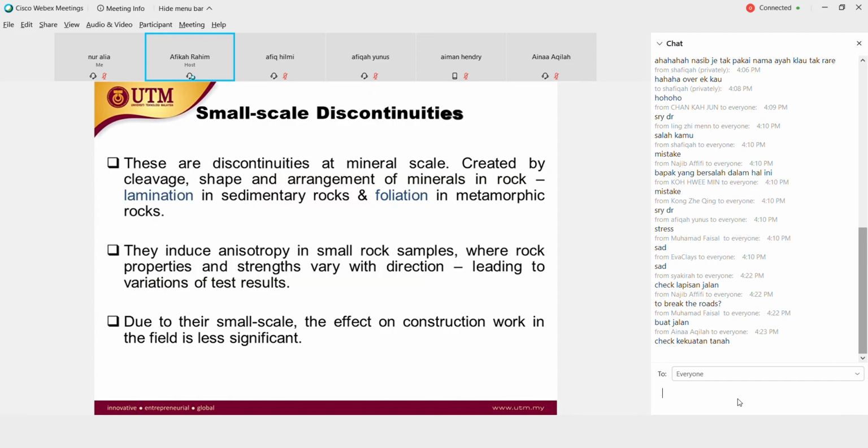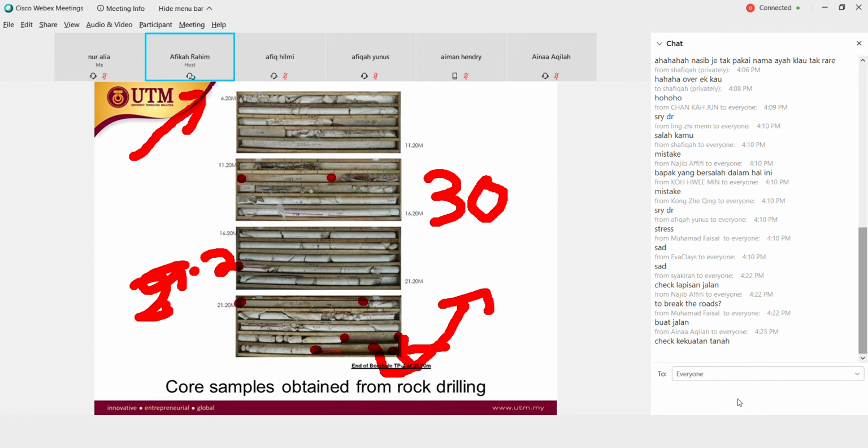This actually will help the civil engineer in determination of the depth, determination of the strength of rock, and also determination of cavity. What if we couldn't get granite? For example, say this one is granite, altogether is granite. What if this one is mud? It's a muddy material. It's not rock. So we can't core. If you core, it will lose down.